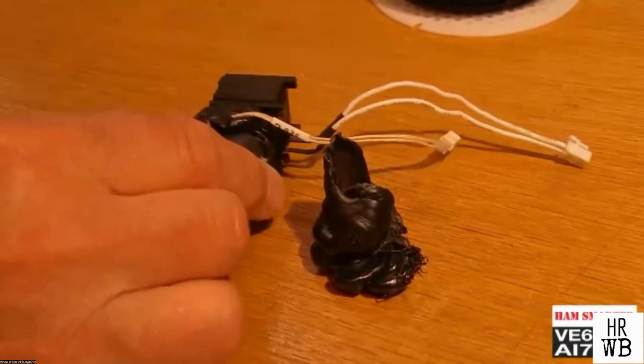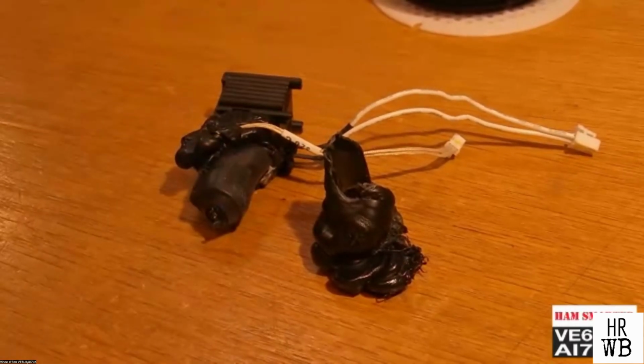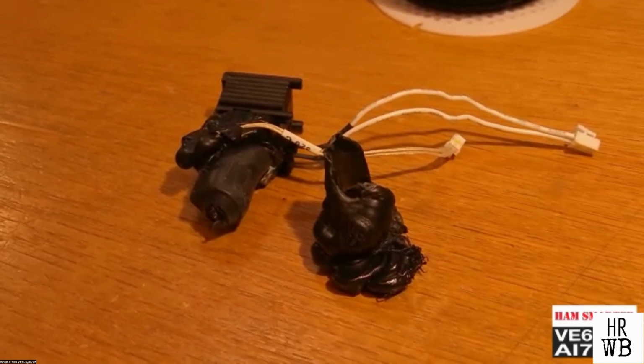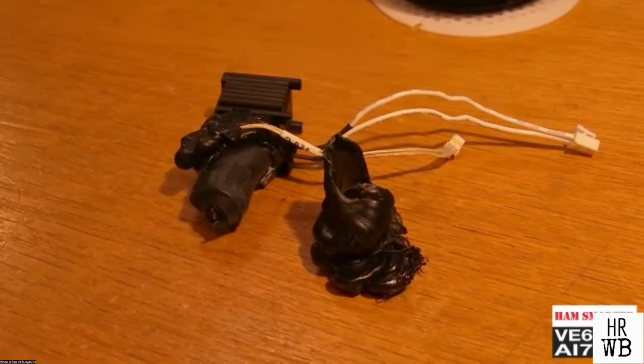And I went away at lunchtime yesterday for a little bit, and I came back only to discover my print had dislodged from the build plate. I later discovered that I was in a rush and I neglected to properly, in software, make sure it was going to stay on the build plate. I just kind of dropped the object there, and I forgot the whole lay flat thing that Mrs. Zafiropoulos taught me. So anyway, that caused my hot end to have a backup of Orwellian proportions.